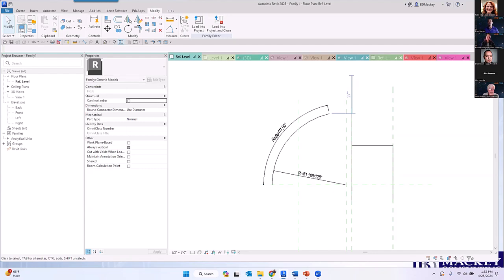But there are ways to go out to IFC and bring the IFC into Revit. There's ways that people are using like Rhino inside Revit to do things like that. There's a lot of different workarounds to do that. It looks like somebody actually even put it in chat, so thank you for that, Samuel. But the problem with all this is if it's a parametric family, you lost it. It's done. So there is no way to take a parametric family back.